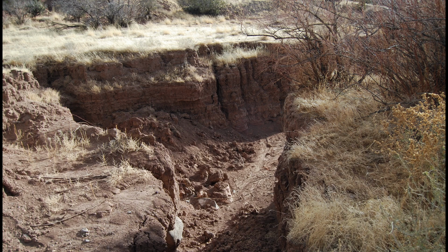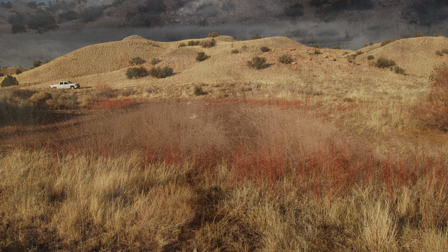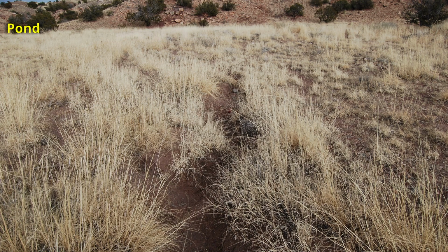We're going to look at what happens when a poor job is done building a spillway for a wetland. This is a constructed pond on a ranch in Arizona. We can tell that the pond sometimes holds water because willows are growing around the edge and the basin has exposed soil. We walked around the dry pond to find the spillway. Water leaving the pond had formed a ditch in the spillway.